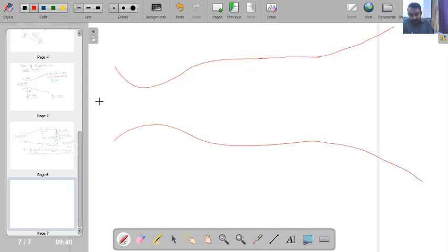Here I have PO, this is the exit point E, with Mach number of 3 and pressure of P exit, and this is a constant area duct. This is the point where I have the normal shock wave, so this is point 1 and point 2, and after that I have once again a variable diverging duct, and from the diverging duct I have the exit at the ambient.